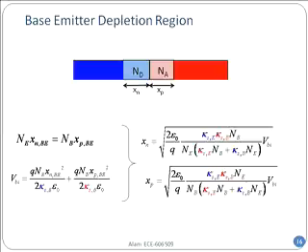And that is the whole point about the heterojunction bipolar transistor. I do not have any problem anymore with the Early effect because my base doping is large. So no problem with that. And correspondingly, my Kirk effect is also suppressed because now I can raise the collector doping. So all those problems are gone because I can take advantage of the gain, get a lot of gain from the band gap difference. You see, that is the central point why we do this.